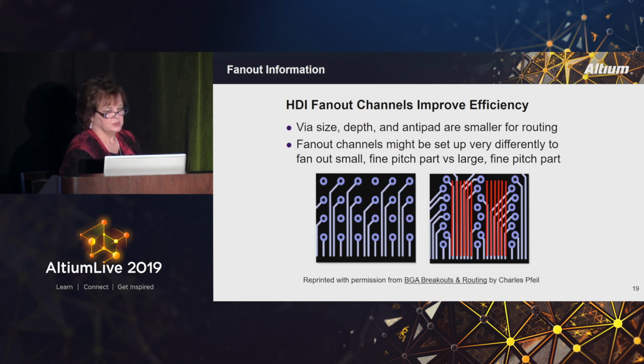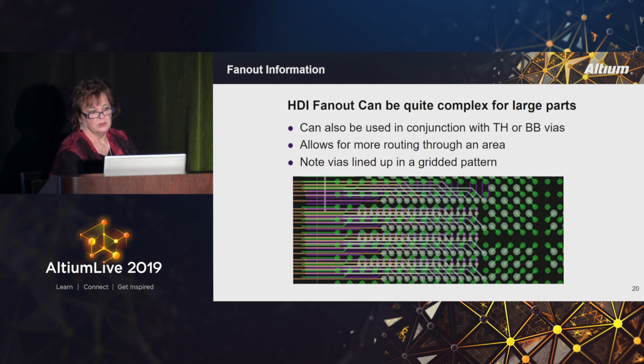So there's multitudes of patterns. I've worked with thousands of different patterns for setting up those vias. These in particular are from Charles Pfeil's book. It's a wonderful book about fanning out large, fine pitch BGAs. He really doesn't talk about small ones. The name of it is down here if you're interested. I believe it's free and it's on the internet. So this is one of his patterns here that I happen to incorporate to show you things that you can do. This is one of my patterns.